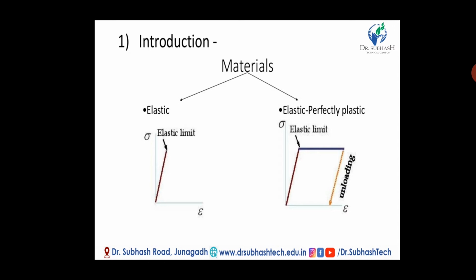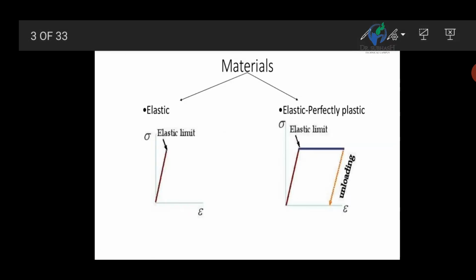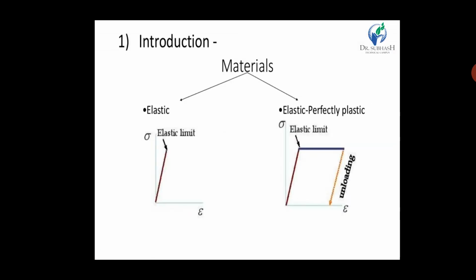The working stress design limits the structural usefulness of steel to allowable or permissible stresses, which are below the elastic limit, called the yield stress, and it is taken as the design criterion. In the plastic method of design, the ultimate load is taken as the design criterion, and hence a structure designed using the working stress method may be heavier than one designed by the plastic method.